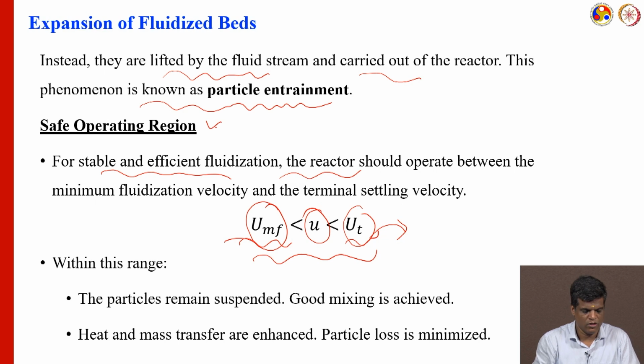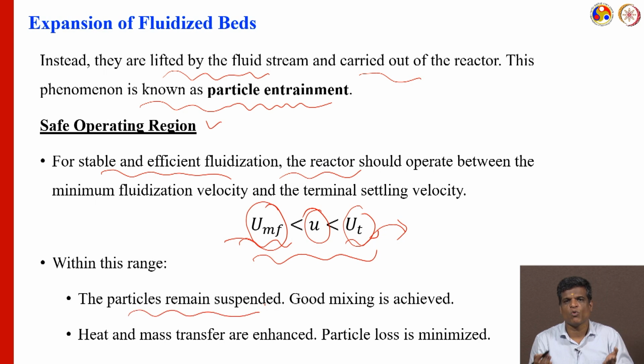For safe operation of the fluidized bed within this range, the particles definitely remain suspended, and we get very good mixing. Heat and mass transfer are also enhanced. Particle loss is minimized here, because it is working in the proper operating conditions, the safe operating regions.